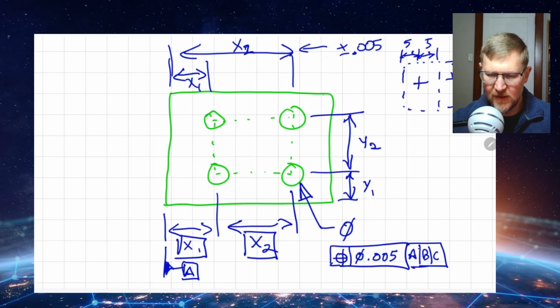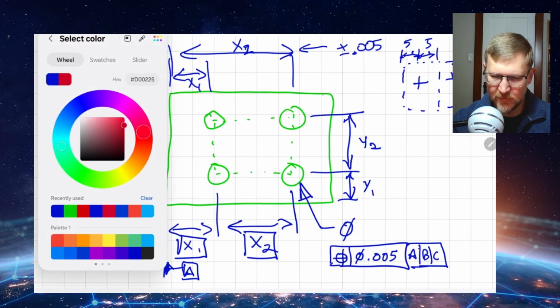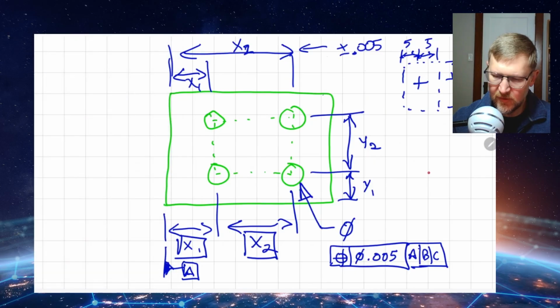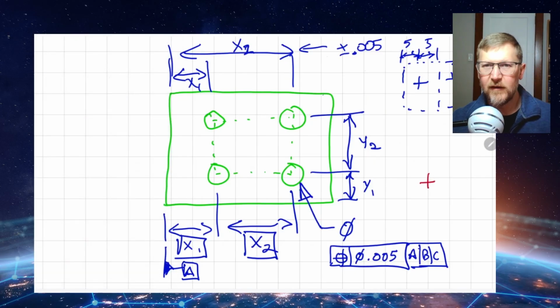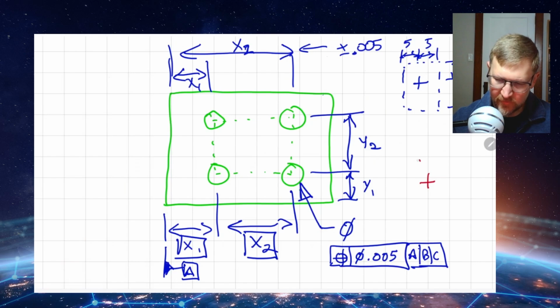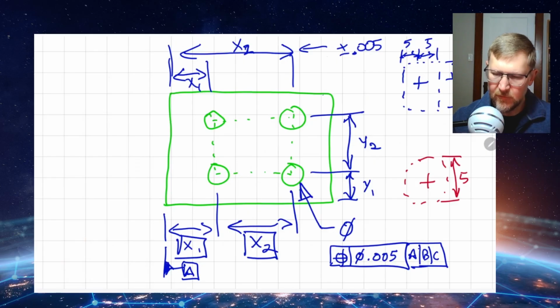So that's the pattern you would get if you're following a traditional linear dimension. Now, if you use a GD&T approach, this defines your tolerance down here in terms of a diameter, and it basically says the whole width of that is 5. Right, but what you see is if you're comparing that plus or minus 5 versus a 5/1000ths diameter, it's a little bit tighter.